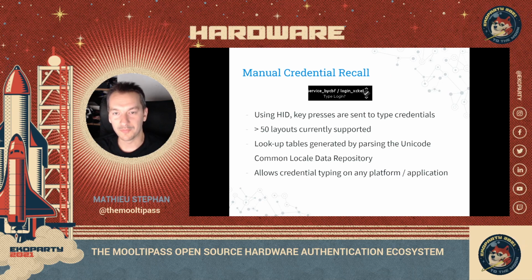Here I'm going to go a bit deeper into the details of how the keyboard protocol works. So when you use your keyboard at home, it doesn't send characters to your computer. It sends some bytes. The byte to character translation is done by the operating system. This is your layout. On your operating system, you can select that your keyboard is French, or English, or whatever. So whenever the computer sees the byte, I don't know, 32, it will translate it into an A or B.